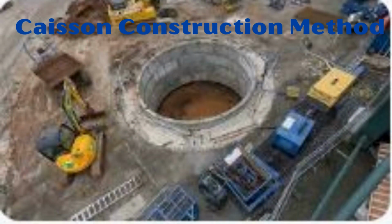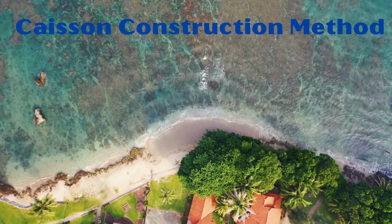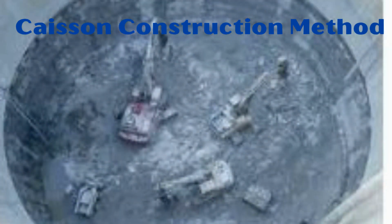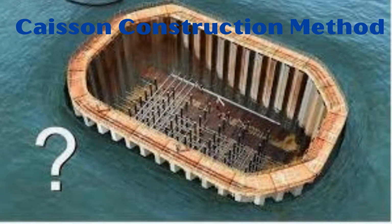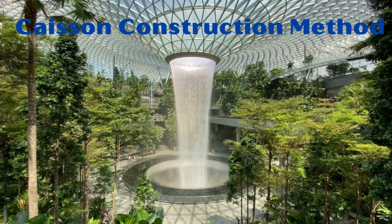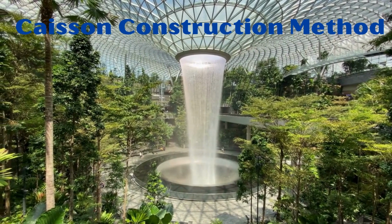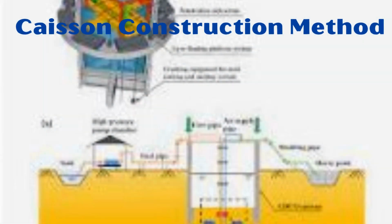Steps in the caisson construction method: 1. Site preparation. Description: clear debris and level the area where the caisson will be placed. In water, the area might be dredged. Importance: ensures a stable starting point for the caisson installation. 2. Fabrication of caisson. Description: construct the caisson using reinforced concrete, steel or timber, depending on the type and application. Importance: the design must withstand the pressures and conditions it will encounter.